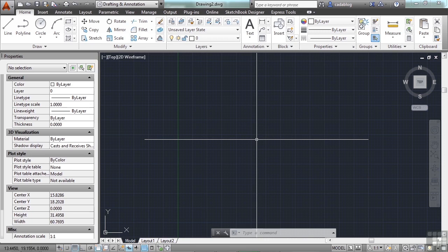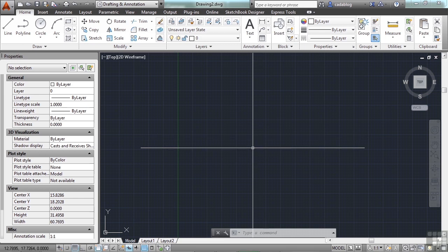There are many ways to create blocks in AutoCAD. Any drawing can even be used as a block, so you can start a new file and draw a block there. Later, you can insert that file with the insert command. Now it's a block in your drawing. Or you can combine objects in your current file to make a block inside it. Then you can export that as a block or as a file to be used later on.